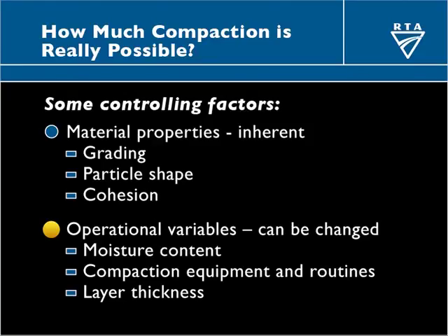Clearly you've got control of that. And the layer thickness. Now that one is fairly important. I can illustrate why based on some evidence that we've obtained recently in attempting to compact a select layer in a 300mm single lift, all from the top. Now this was tested in detail to determine whether we were obtaining the full compaction through the layer, which was the point we were concerned about.